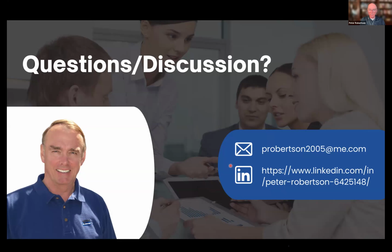One is, do the CPT in the wet season, which would be the preferred way because that's going to give you the lowest answer. But if you can't do that and you can only do it at one time, and you want to correct for it, then there is a way of correcting for it. For bigger projects, like mine tailings that I do, where the structures are much larger, we go much deeper and the overburden gets quite a bit higher.